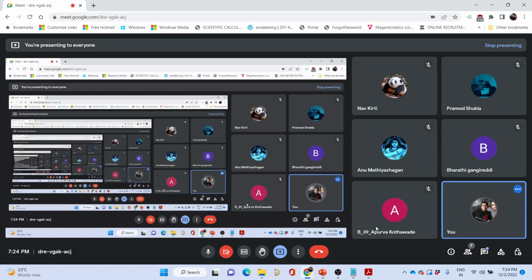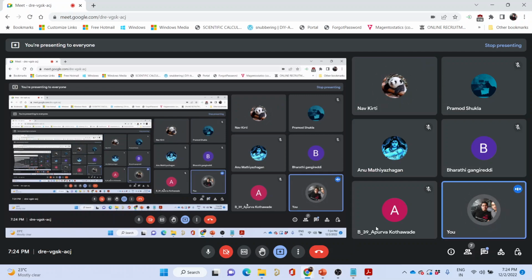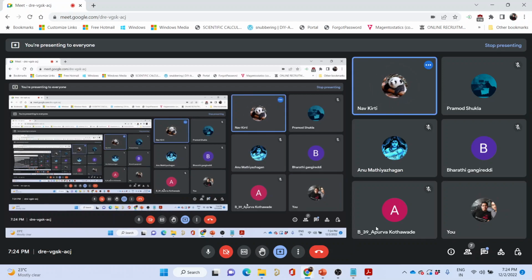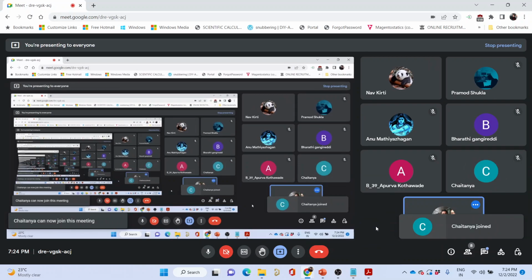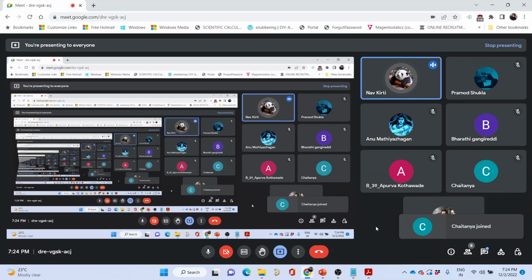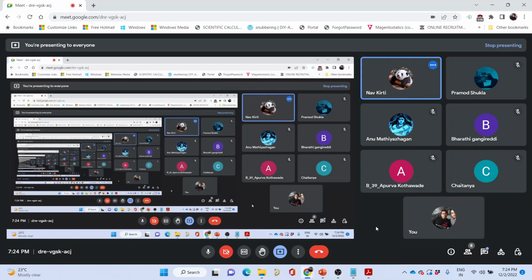Have you heard anything of voltage second balance? Yes, sir. So what is voltage second balance, and is it necessary to have a voltage second balance? So average voltage zero. Across whom is the average voltage zero? Inductor. So what does that actually imply? Whatever energy is stored, it will be discharged. Discharged where? So to the load. Okay.